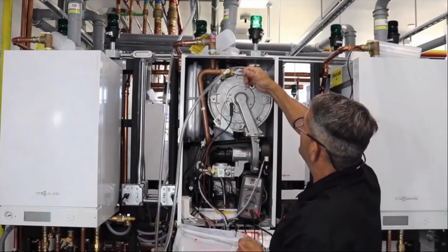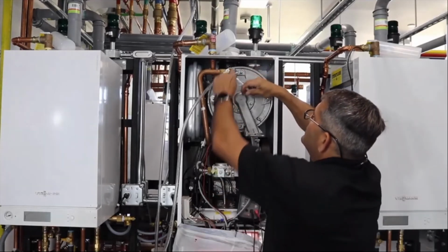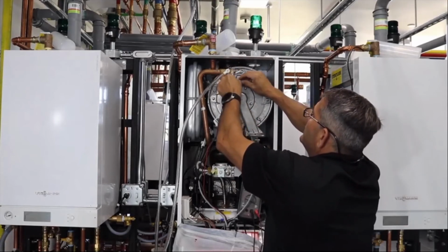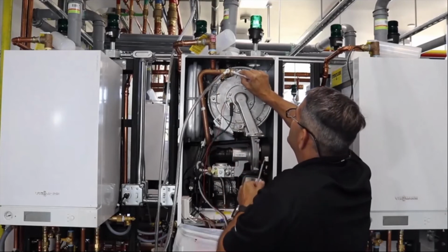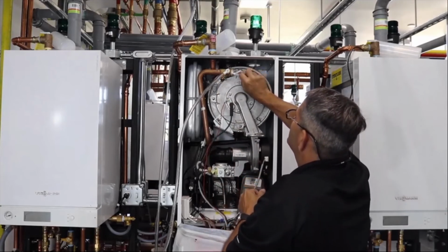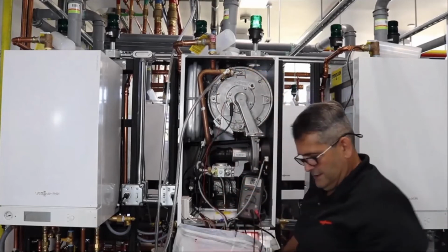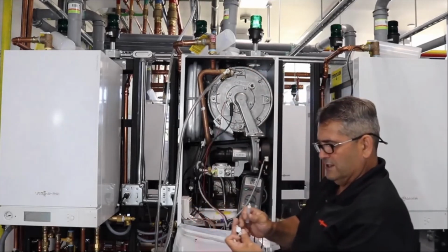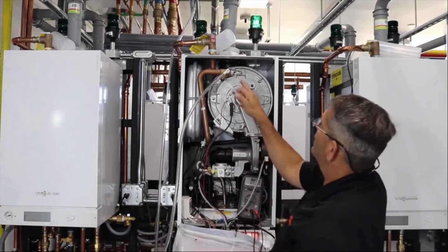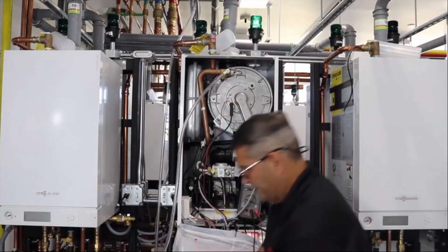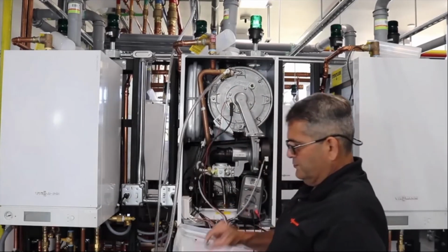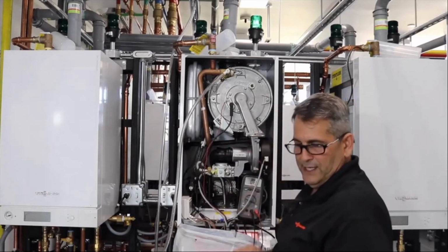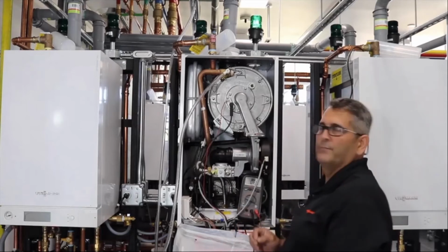apply a fair amount onto the brass part where the sensor is going to meet up. And I normally just spread it around, just so you'll get a nice heat transfer on there. So you can do it either way. You can put it on the sensor itself or on the thing. I just don't like to get it all over my hands. All right, so I do get the new sensor now. I have the 2 new screws. I put the heat paste onto the brass part of the boiler itself.